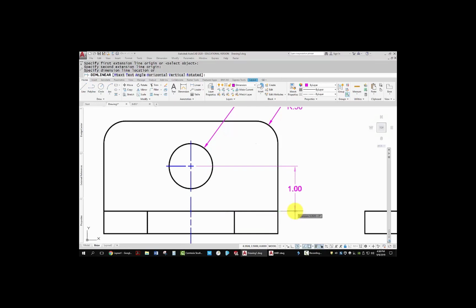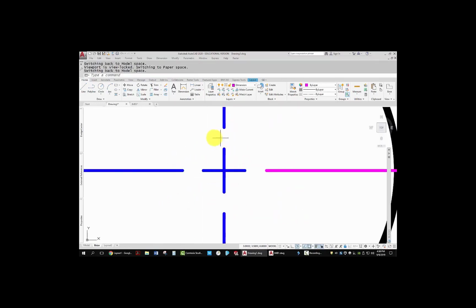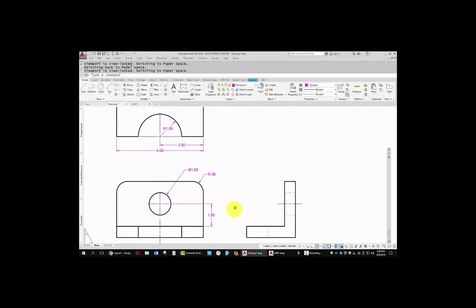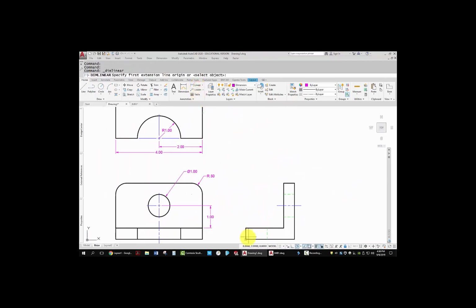I go to the end point of the crosshair because the way I've got the dimension style set up, you get the crosshair with the gap automatically. Come back over to the other side. We'll do another linear dimension from here to here. We'll go over here, 0.375, DBA for dimension baseline. Grab that point.